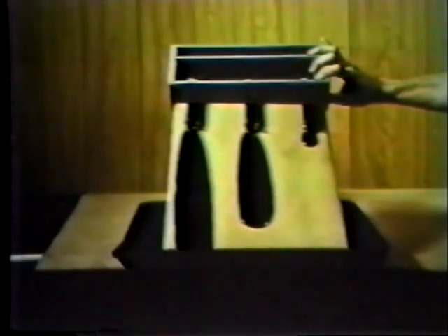The reason we have so many asphalts, types and grades, and you're going to see all told about 16 different types by the time we're done today, is to control the viscosity, because that's the characteristic that affects most how efficiently we can mix the material with the aggregates we're encountering. For example, if we're trying to mix asphalt with fine sand, we're going to need something fairly thin to get it to coat and mix with something fine like talcum powder.